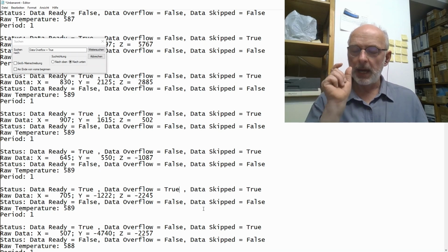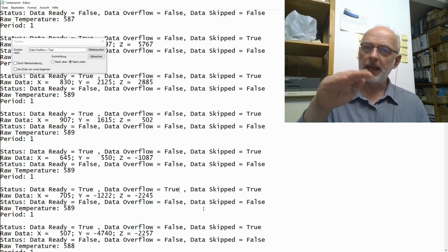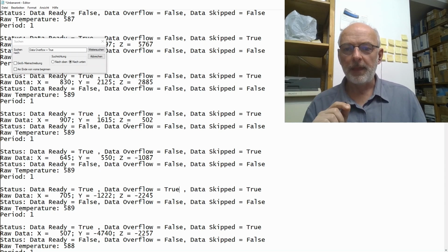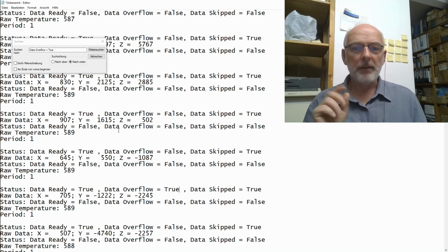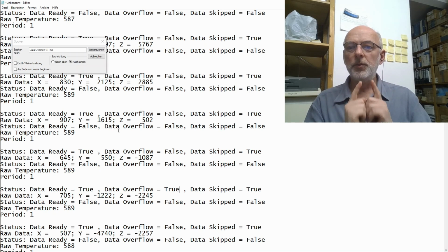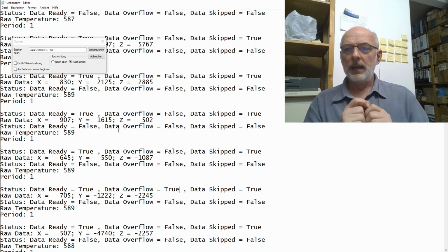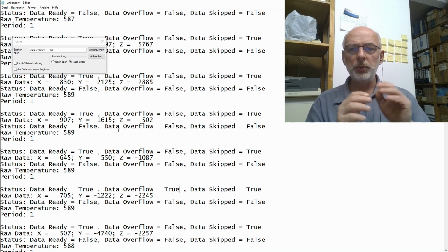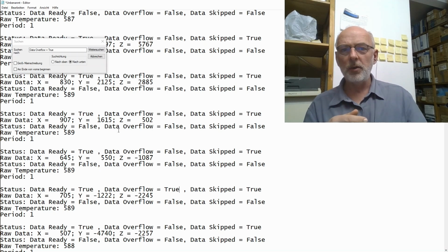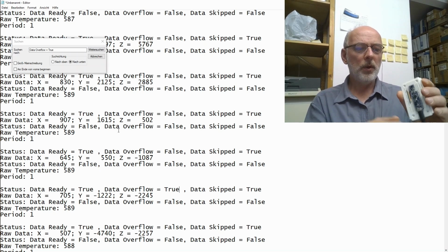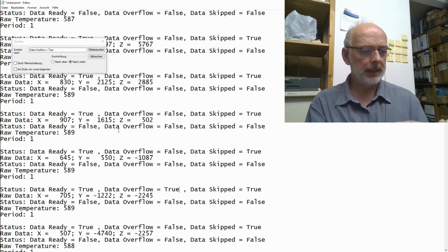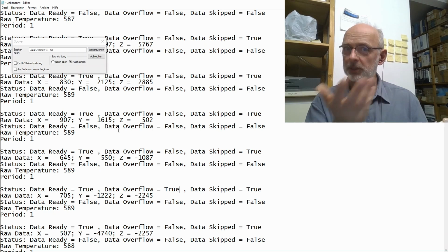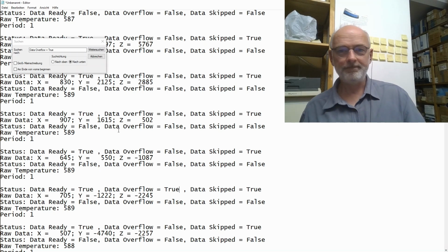Yeah, no problem. We are at the 2 Gauss range. We can up that into the 8 Gauss range, and then this should be gone. However, the main problem I want to solve here is, of course, first we have to handle errors, and beyond just printing out there was an error. And second, I want to streamline the communication here. And there is a 5th pin, you know, an interrupt output, data ready. Shall we use that?